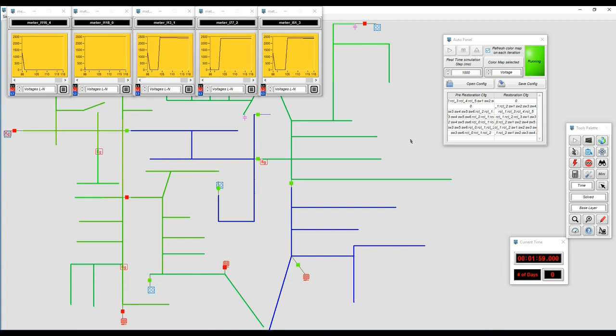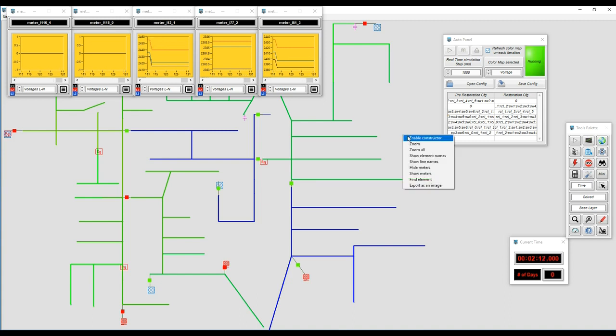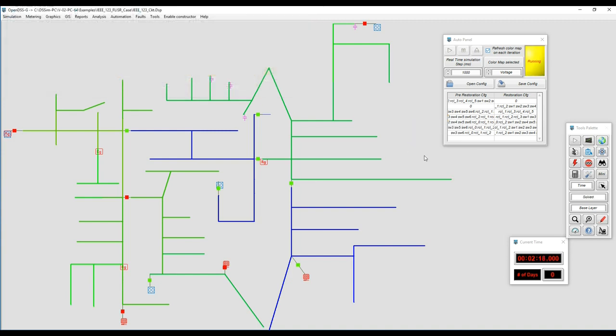And after that, we can see also that the regulators connected to zones in which we have voltage are trying to do their job and they're taking the voltage to an acceptable range. Now, you can see that zone 4 is connected to zone 5, or there's a tie switch in between, but it didn't operate. It's because the tie switch that energizes zone 4 cannot hold the extra load in zone 5. So if we try to close that circuit breaker manually, we're going to trip the recloser that gets connected to the other feeder. And let's try here.